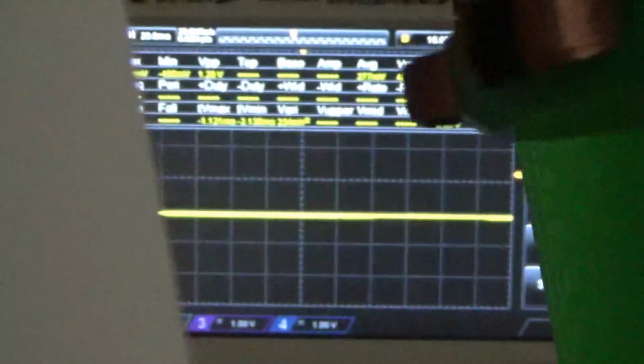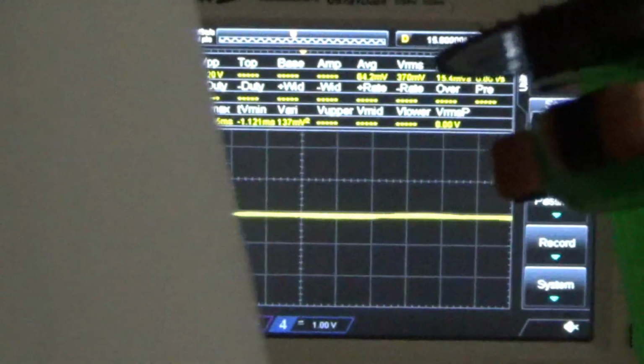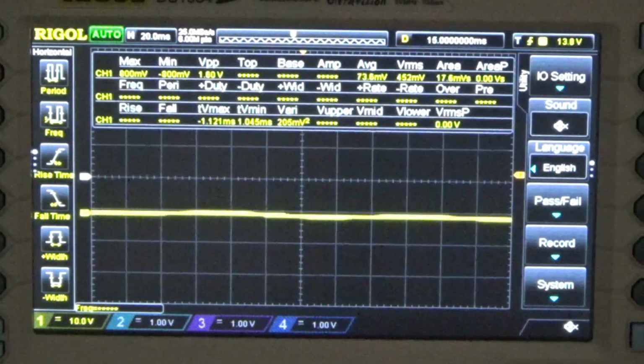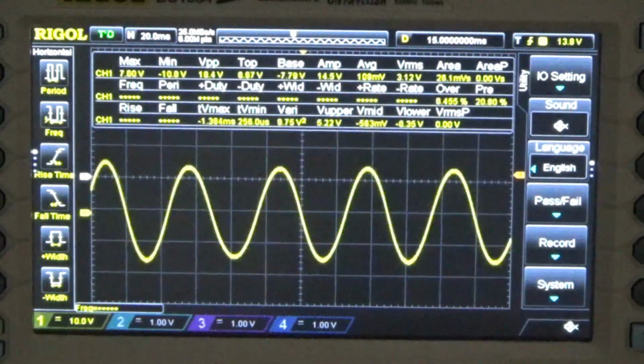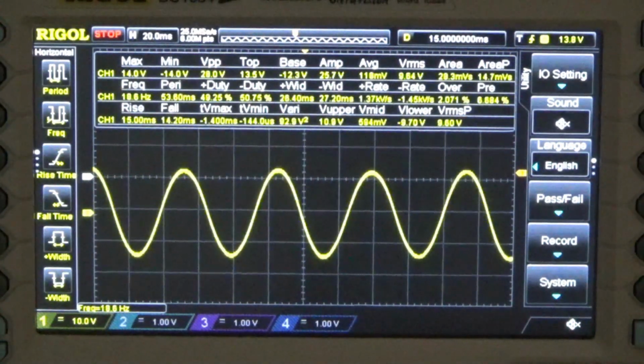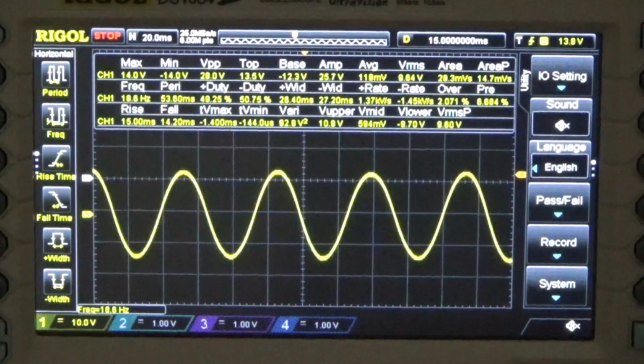Okay, I put a few washers in to space the magnets from the coils a little bit, to try to derate it a little. So I'll give it a spin, do a single sweep. Let's see what we got here. Okay, the last one was about 46% too high.